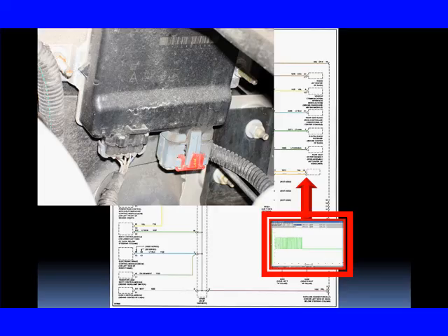If we have signals here, we've got to make sure that the signal here is the same as the signal on the bus. Why is that? Because the signal on the bus is communications for all of them. If we see a signal here that is not identical to the signal on the bus, we use a dual trace scope and compare them. That's telling us that the TAC module may be trying to communicate out, but since it's not the same signal as the signal that's present on the bus, it's not making contact. We've got an open circuit.